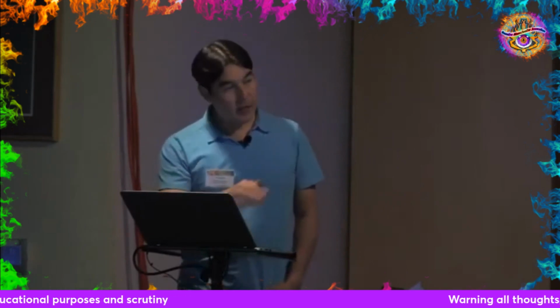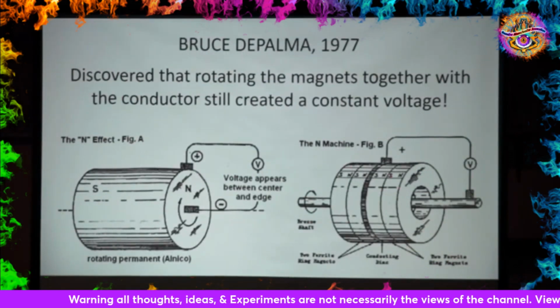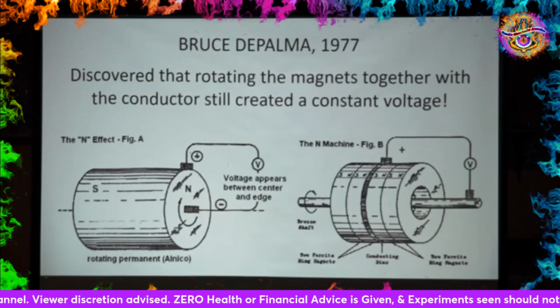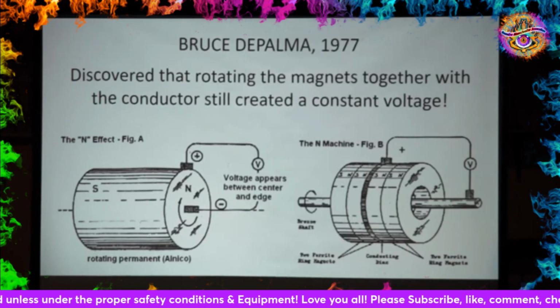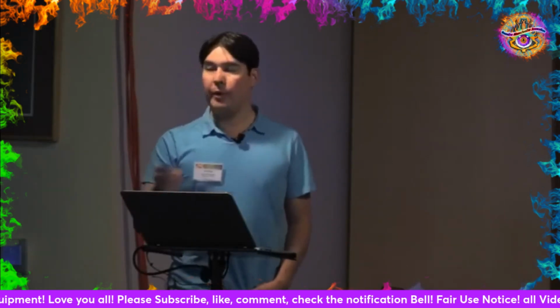And so the second image, in figure B, is basically two sets of magnets on either side of a conductor. That thing going down the middle is basically a copper disc, or it could be brass or any type of non-ferrous, non-magnetic metal being used as a conductor. And the same thing: if you have a shaft running through there and you rotate that, you get a voltage potential difference between the perimeter and the shaft. But again, in any of these configurations, they're always going to show current, but virtually no voltage.